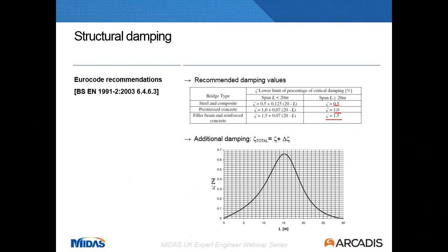The problem with that is, since you have to run one analysis for every time step, for instance, if you are using 1 second of overall time and 1 millisecond as a time step, that's 1,000 steps. That means running 1,000 analyses, very time consuming. And the other problem is with the time step, the errors can propagate much more easily than in modal superposition. So with time integration, you should go to even smaller time steps to avoid any numerical problems. But modal superposition is much more stable.